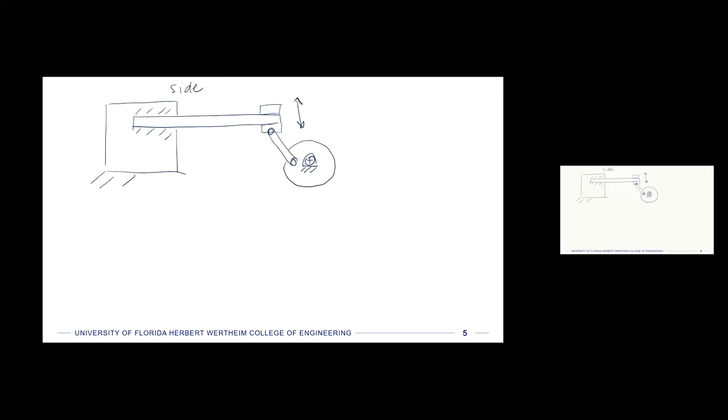This one is a little bit more unique because you can change the mean stress. If you just have it as a fully reversing stress like that, that's fine. If you move the center point of this drive upward or downward, then you can change the mean stress. So you could move it up to something like that, and then do some experiments that way. If you had two identical specimens, you could slowly change the mean stress and look at what happens there.